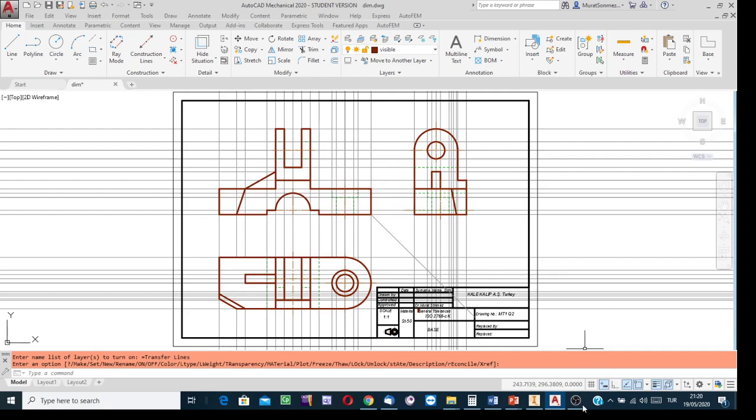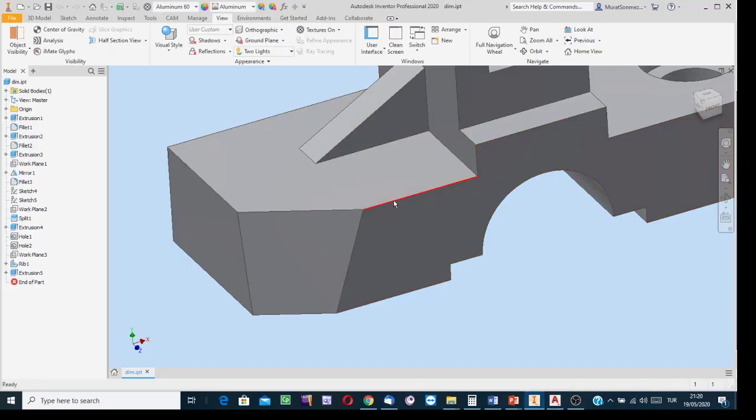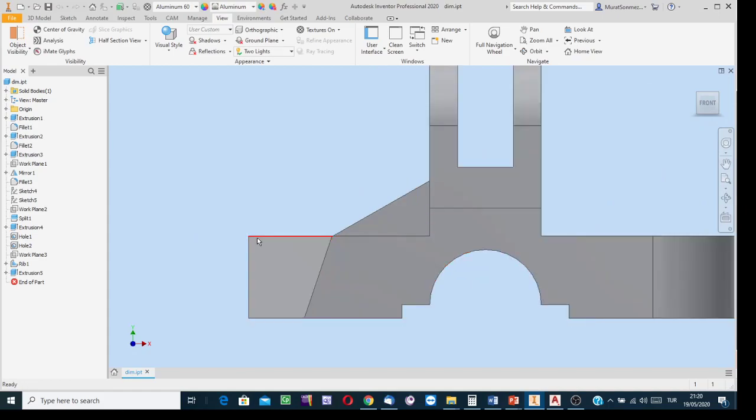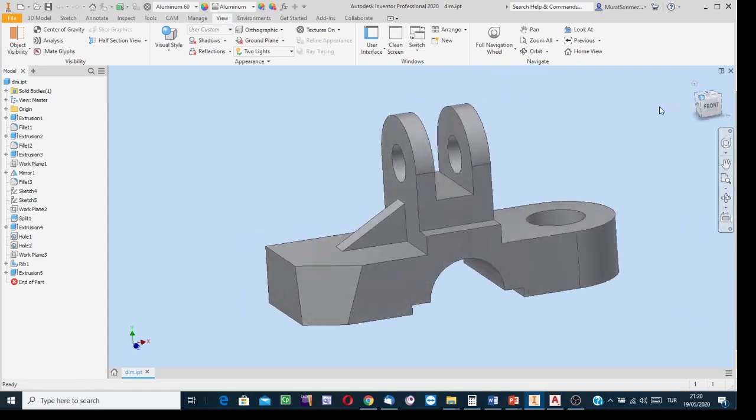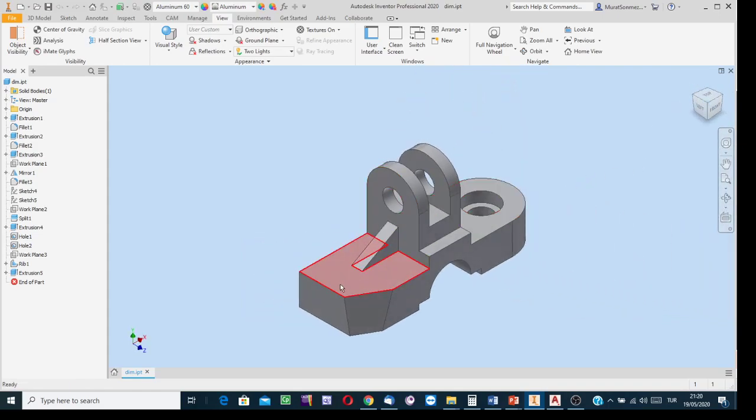The joining lines mainly will be what? Intersections or the edge view of a surface. For instance, there is a surface here. While we're observing the object in this direction, we see a line, but that line on the view corresponds to the edge of this surface entirely.